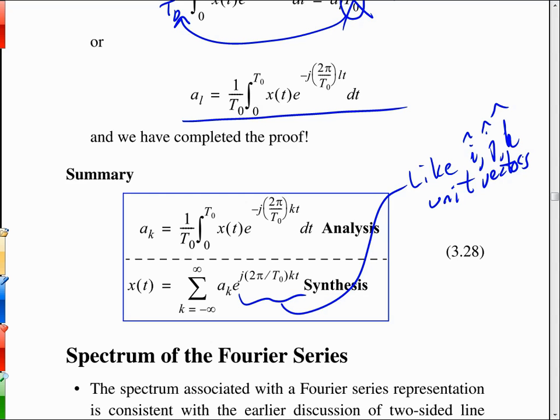I say it's valuable because if we have an arbitrary periodic signal, we have an interest in what its harmonic content is. We might use that to design a filter to eliminate some of the harmonics that we think could be harmful to our system. We might try to modify certain harmonic content to change the nature of the signal. In music, changing the content of the harmonics changes what's called the timbre, which is the sound an instrument or a singer's voice would have. Could be better, could be worse.